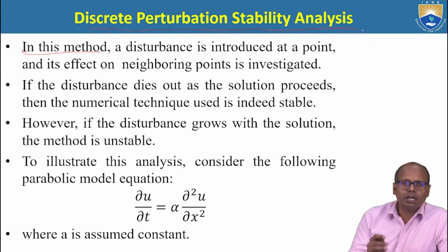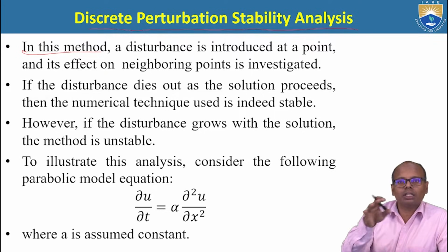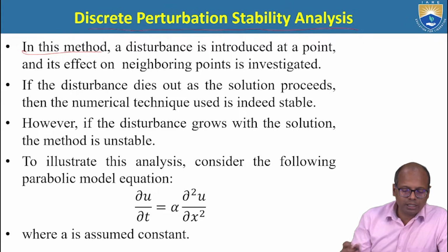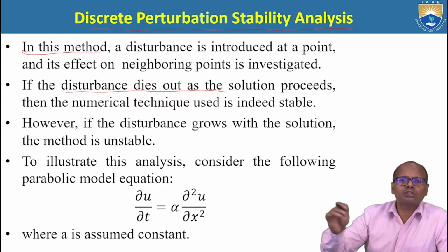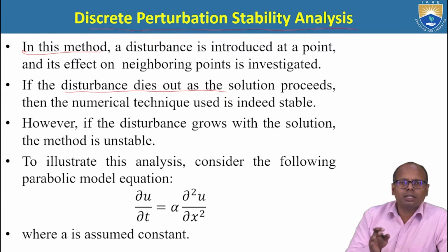What is the essence? We will introduce some disturbance at one point and we will see the effect of the disturbance on the neighboring points. So that is the analysis. Now, if the disturbance dies out or if it decays with time or if it decays as the solution progresses, then the numerical technique that we are using is a stable one. If it grows, then we call it unstable.